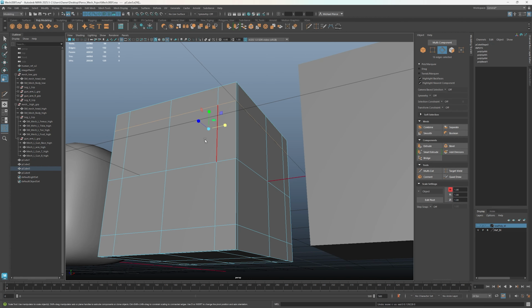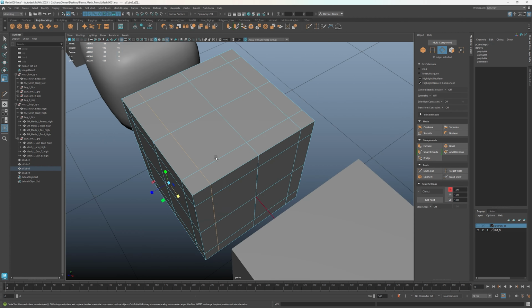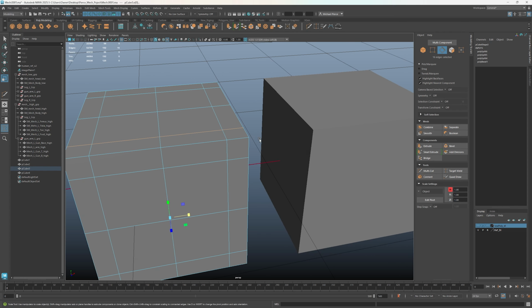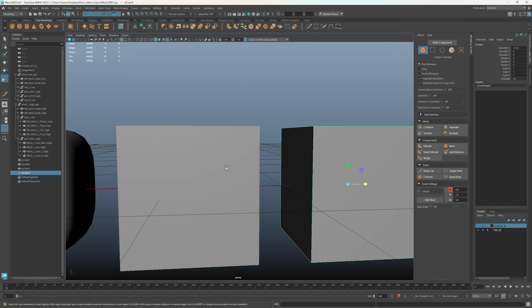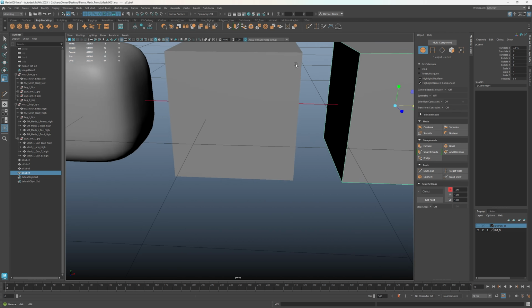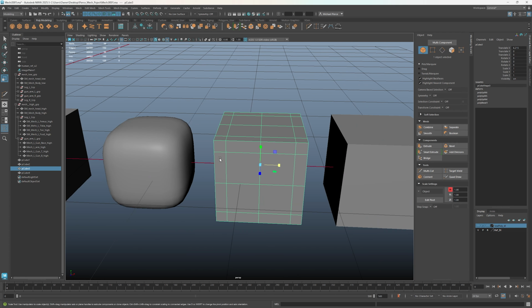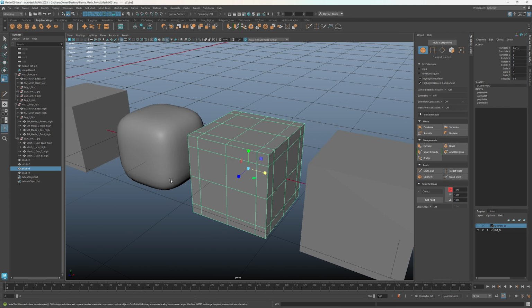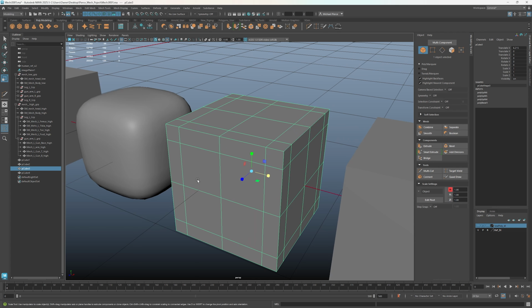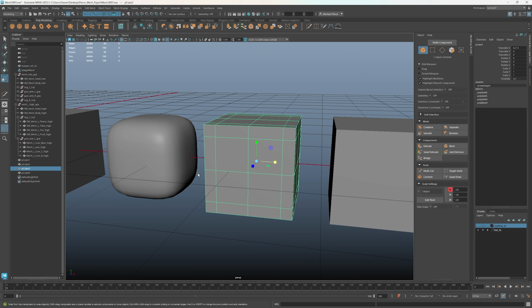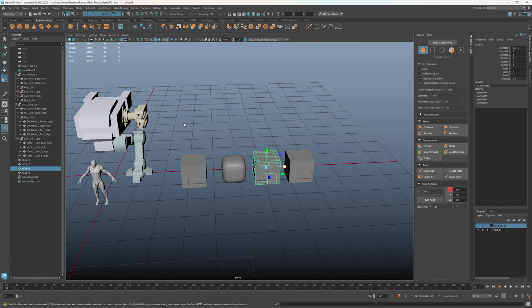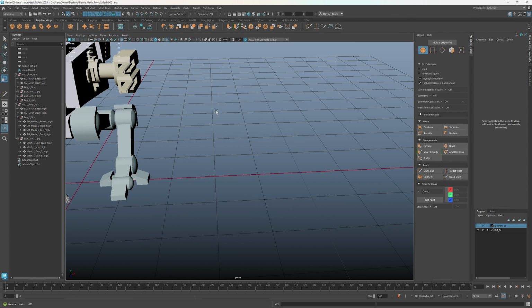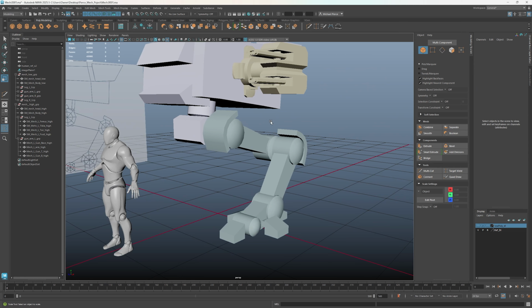Oh, I went a little too far on some of these, which is why you saw that it was looking weird and wonky, right? You want to make sure that you have more even topology, especially if you were to be bringing this to a sculpting program, or if you wanted to displace something, right? So displacements is where you actually give the illusion or use your height maps to displace the model to actually represent that actual information, right? But we are going to be dividing up our mesh here, or adding control edges and